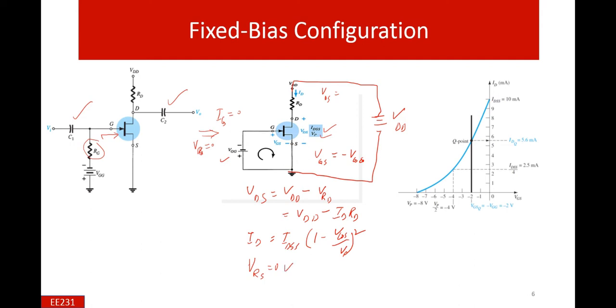And definitely this analytical part will be applicable here, and we can even find these values by using the graphical method, because the behavior of the device is given. This graphical blue curve represents the behavior of the device. This is the maximum current, which is when VGS is 0, and this is the minimum value of the current when we apply the voltage equal to the pinch-off voltage, which is -8. And at half the value of the pinch-off voltage, we find that the current is a quarter. For example, this is an example situation.